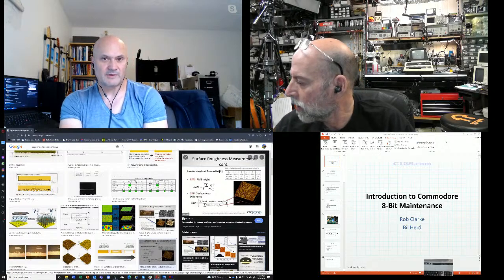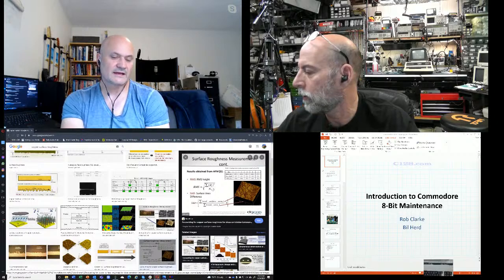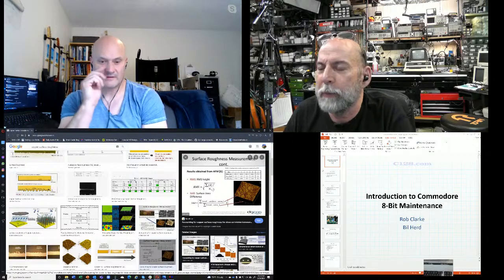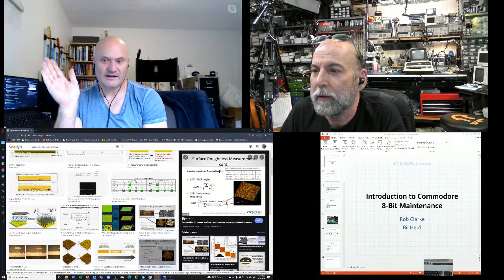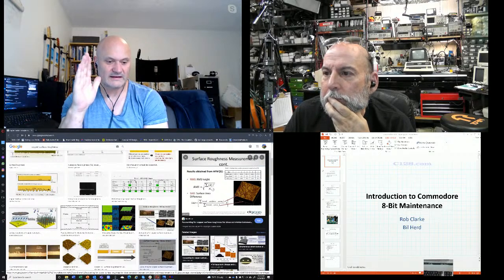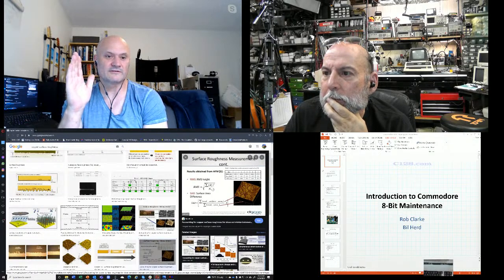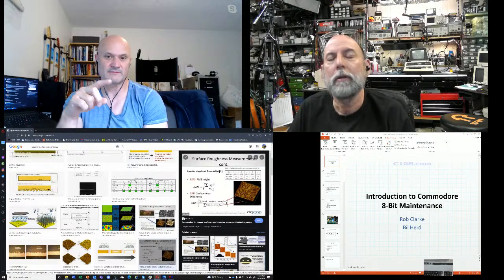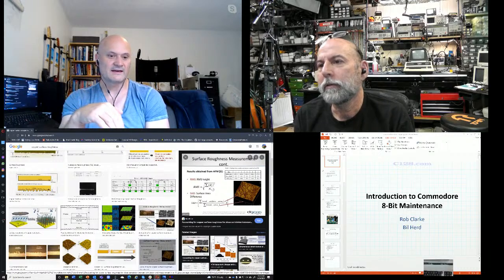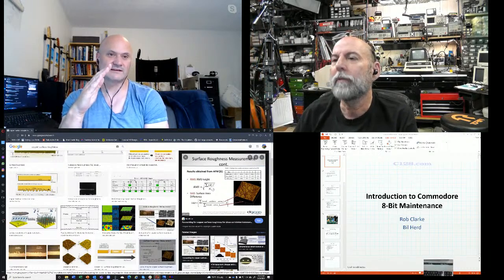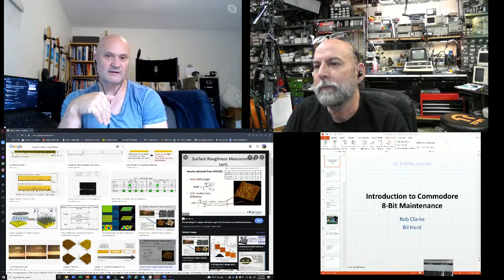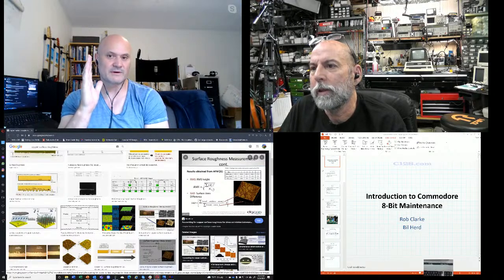Inductance is certainly a big part of it because of eddy currents and things like that. Right, but then there's the physical aspects of it too. And the higher the frequency, and when we say high frequency, we're also talking about a digital signal where you just turn something on and it stays on. It's not about clock speed. It's about the speed of switching. Right, the rising edge. If you have a very fast edge, rise time or fall time, there's a lot of high frequency components to that.